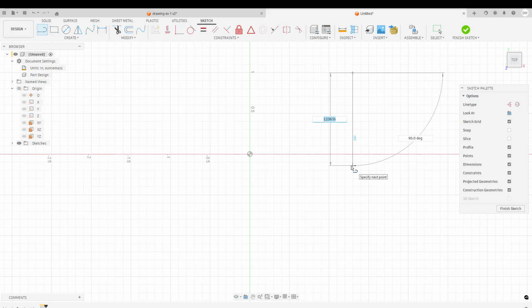So I'm going to type in 1, and to jump back and forth between the dialog boxes, I'm going to press Tab, so it allows me to go back and forth. If you're only putting down one line and nothing else, you would press Enter to close it up and then finish drawing your lines. However, if you're doing a sequence of lines, my recommendation is, instead of pressing Enter, to click a second time to place the end of that line segment.